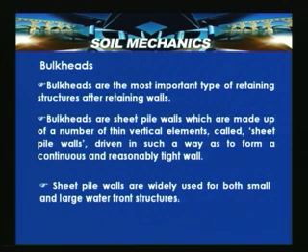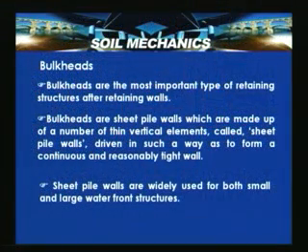The wall is very thin, and it has a range of section modulus which is possible. A typical section can be selected based on the section modulus required for a case. There are also walls like diaphragm walls, which can be constructed by digging a trench, placing reinforcement and introducing concrete.